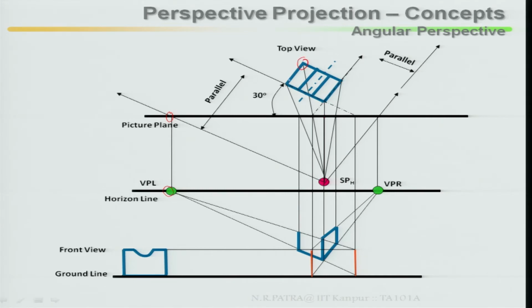This is actually the left face, because this part is your left face. So, you project it back, then this projection has to be drawn along the line moving from right face to left face. You see, this intersection point has come here, then join, then after joining, it becomes easier.